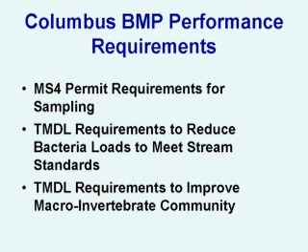This picture shows the cleaning of that upstream side. They actually bypass the creek, and they put in a loader, and they scoop out this material, and they put it in trucks and take it to the landfill. So that's about a once every 2-month maintenance thing. And then the UV bulbs are checked on a regular basis to see when they need replacement.